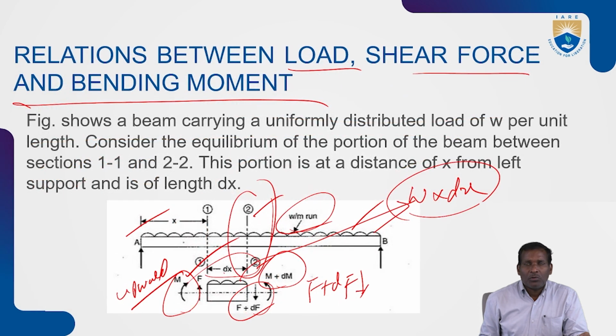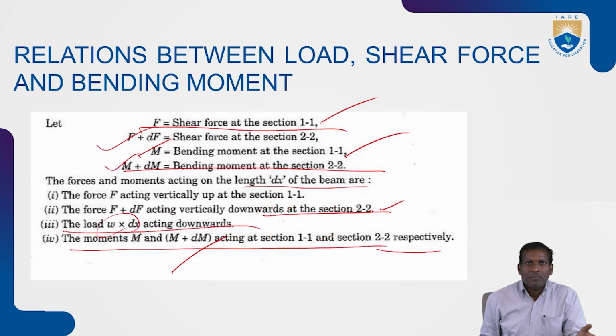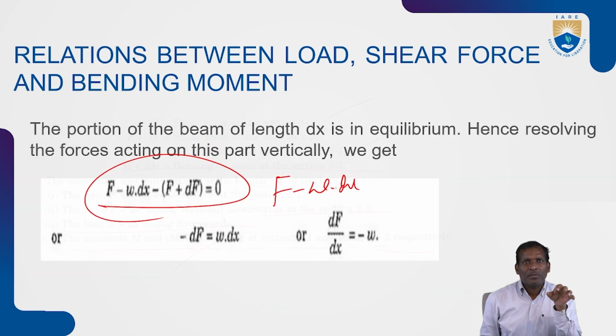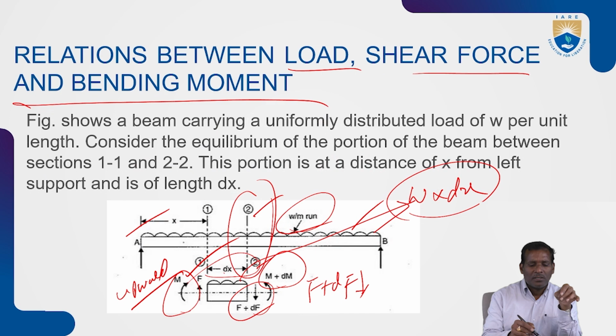And the relation between the load, shear force and bending moment has been derived. We derived it by taking a small elemental portion of the beam of length dx between the two sections, 1-1 and 2-2.